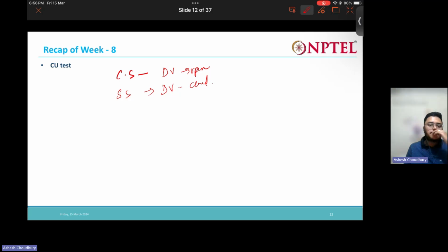Okay, generally. Now the next stage, as I said, is the shearing stage. So what is that? We close the drainage valve. Now again, you are applying the deviatoric load. What is going to happen? Pore water pressures are going to get generated.